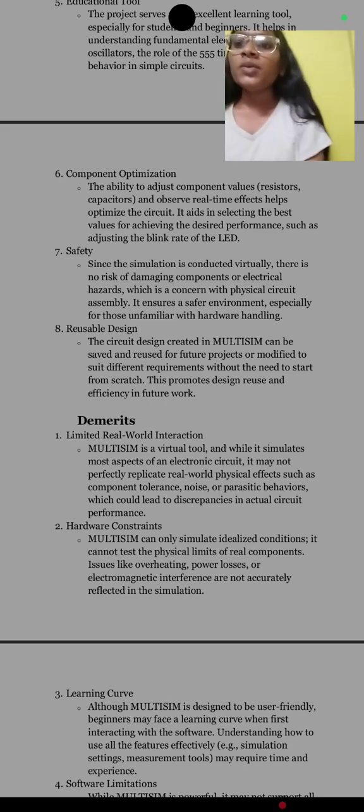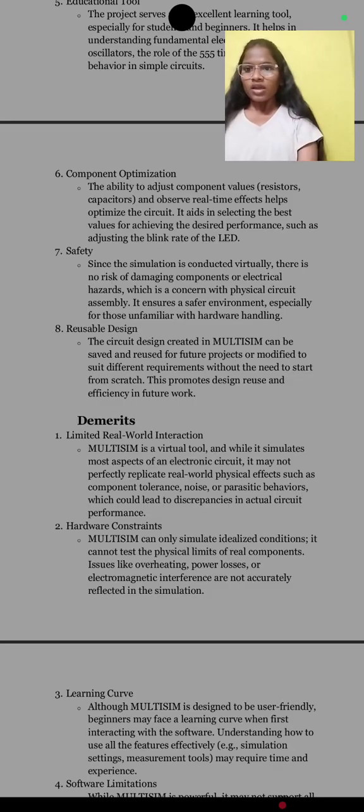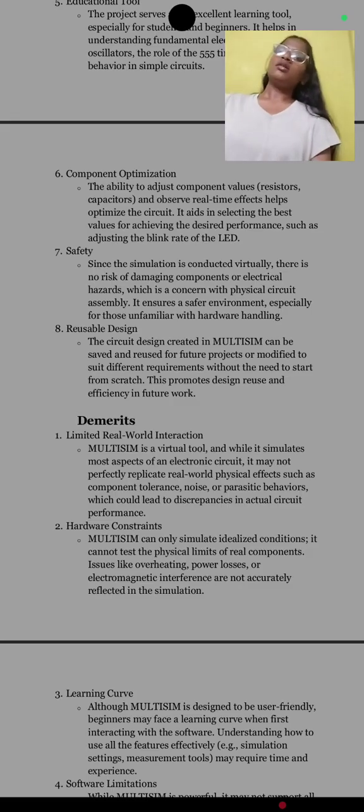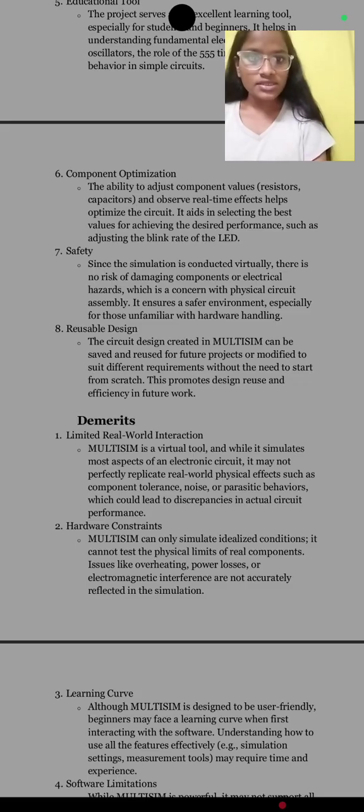Demerits. Limited real world interactions. Multisim is a virtual tool, and while it simulates most aspects of an electronic circuit, it may not perfectly replicate real world physical effects such as component tolerance, noise, and parasitic behavior, which could lead to discrepancies in actual circuit performance.